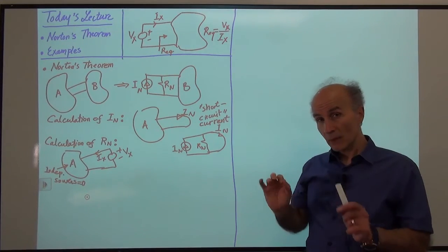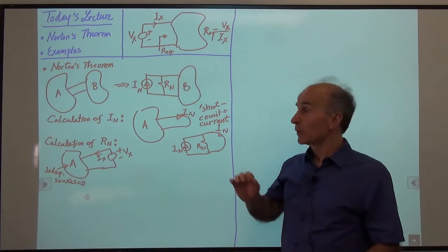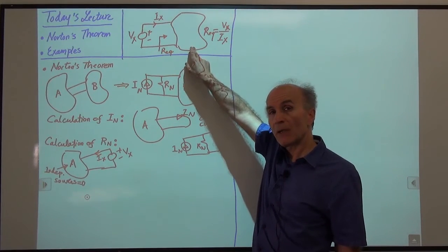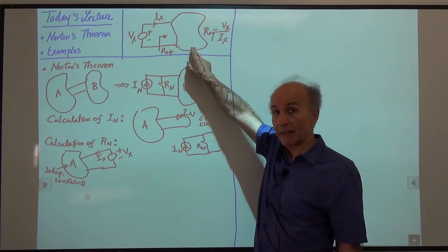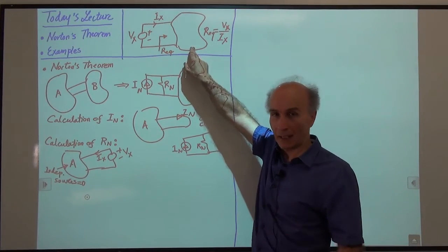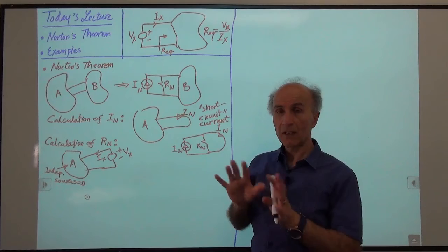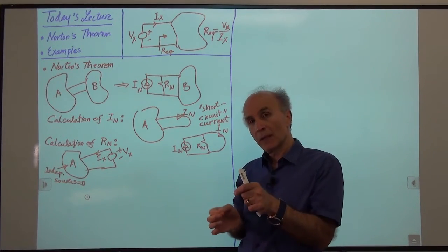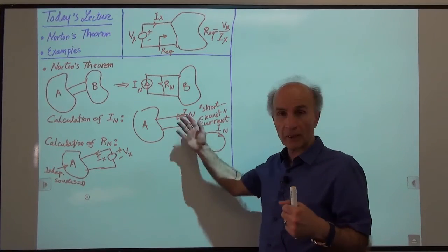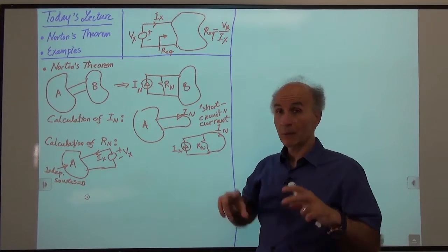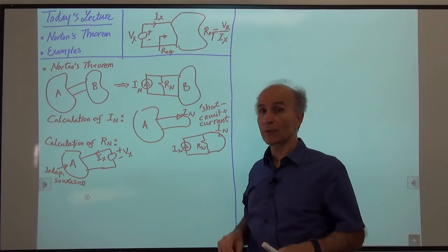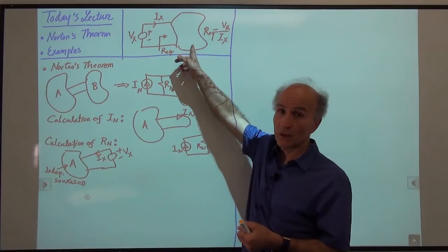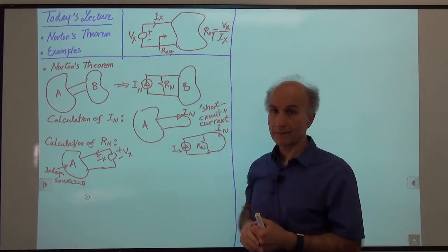One little difference here is that previously when we introduced this a long time ago, we didn't say set all the independent sources to 0. But that's actually what should happen in any case. In any situation, if we are trying to find the resistance between two nodes in any circuit, whether we want to apply Thevenin, Norton or not, what we really mean is all the independent sources in here are set to 0, and then we find the resistance.